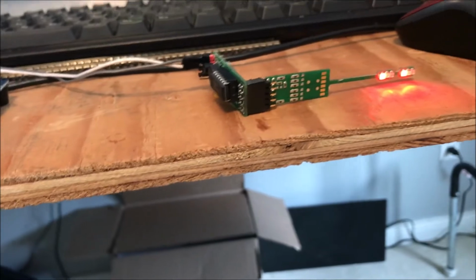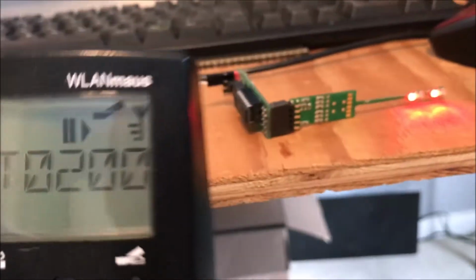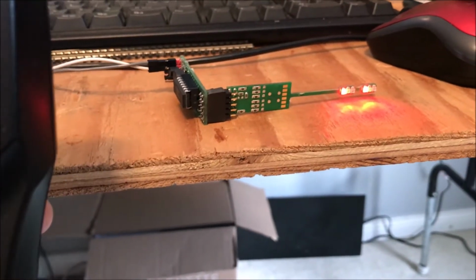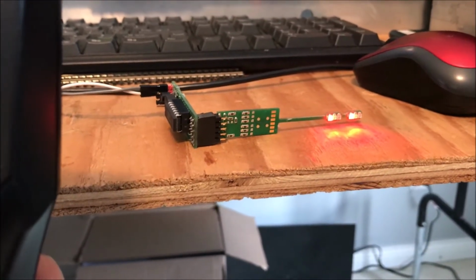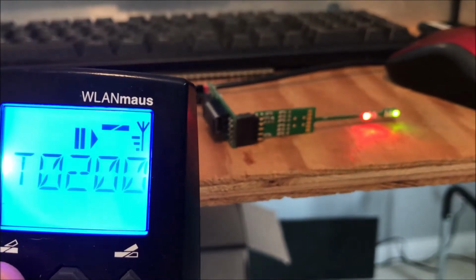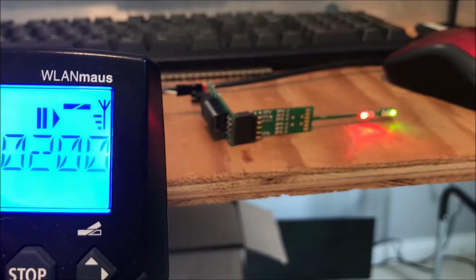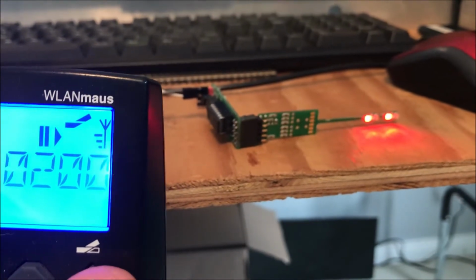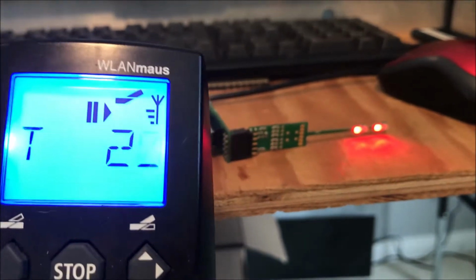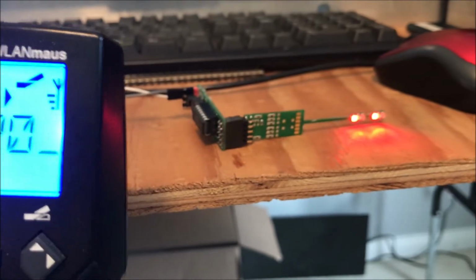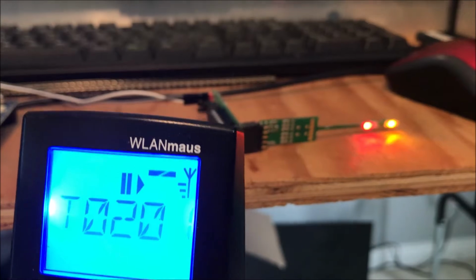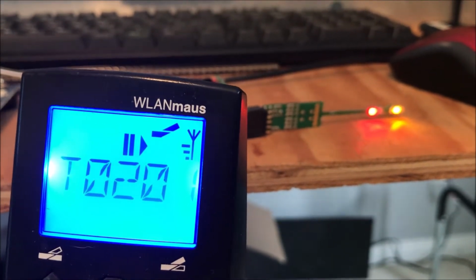So for instance, this one right now, I actually have it set to address 200. Right now, both headlights, sorry about the glare, are showing red. So now if I go 200 and I go close, the top one flipped to green, throw, flip to red. And then 201 will actually control the yellow light for that signal head. So that went to yellow, flashing is close, and then throw is solid.